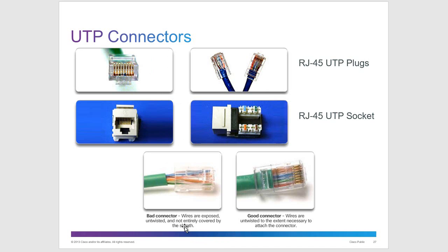The good connector, because you're going to need to know, or at least it's good to know, how to make one of these cables. You want to make sure when you're making one that you have the plastic shielding all the way inside the head before you crimp it down. If it's not, you've got exposed wires that are easily pulled out, and you can just ruin the cable that way. So this is going to be good. This is going to be not so good.